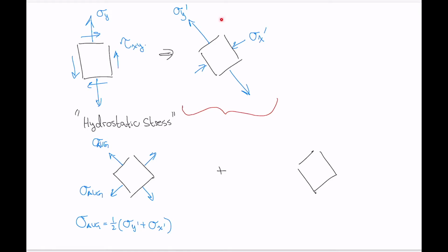the stress state that we started with above here, then the stress here in the y direction needs to be whatever sigma y prime was minus our average stress. Okay, and it's worth noting here above, I should have put this down, that sigma y prime, this is our first principal stress here, and this is our second principal stress there. So let's just do a replacement here and put that like that.